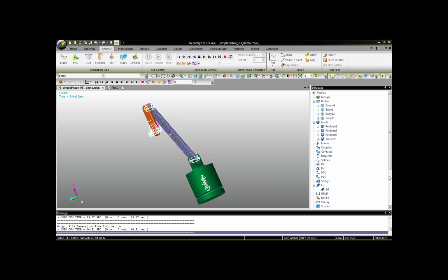In Inventor's Dynamic Sim and FEA, when you use them together, the workflow is such that you start in dynamic simulation. You run the entire dynamic simulation only considering everything as rigid bodies. Then you take the forces and moments applied to a single part at a single time step and analyze that single time step as a finite element analysis model in static stress, only considering that time step's effects.